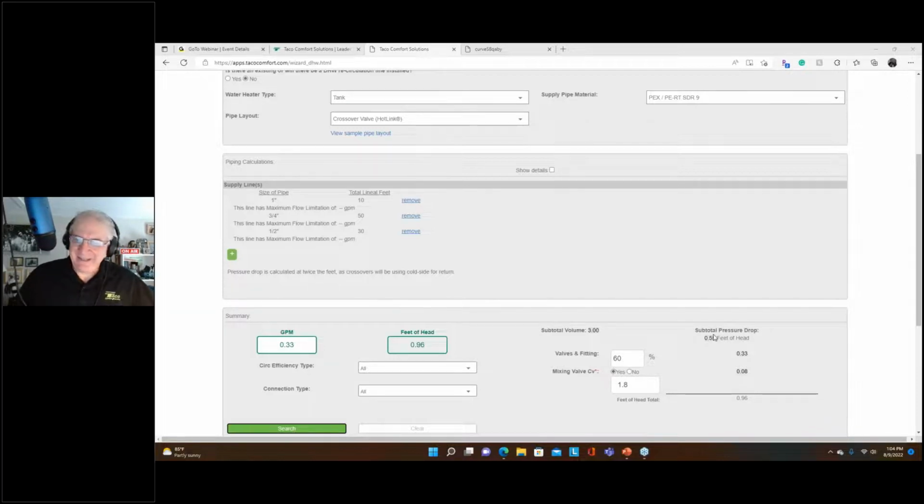And number two, deadheading is one of those things in a closed loop hydronic system with a really, really big pump. You don't want to do it. With a little itty bitty pump, if you deadhead that pump for 10 minutes, is that going to hurt the pump? Not one bit. Not one bit. Been tested, not a problem. Okay, I think we just answered your question.